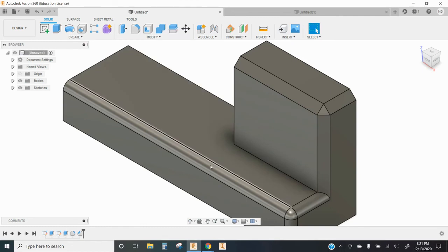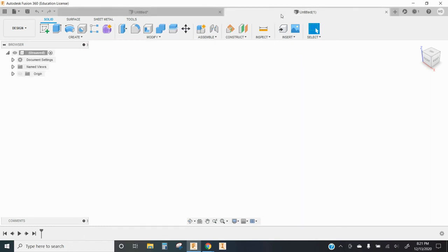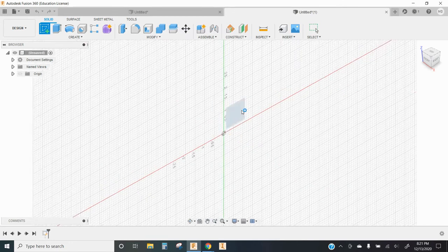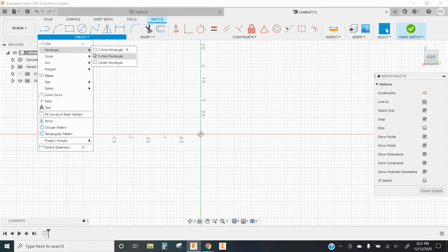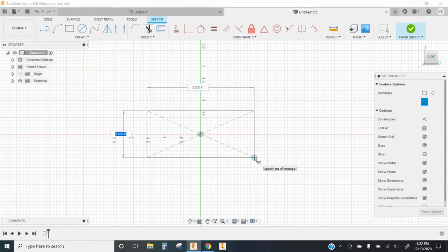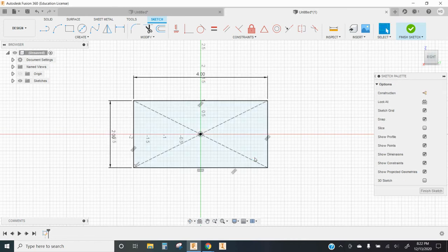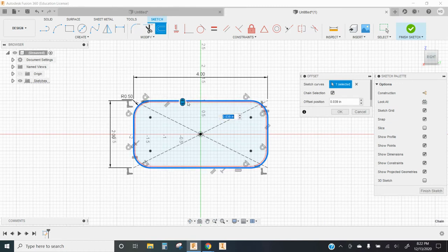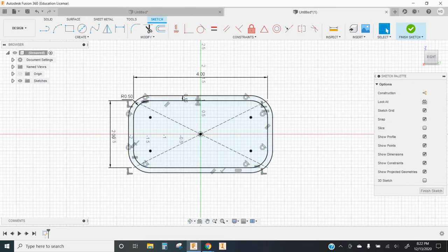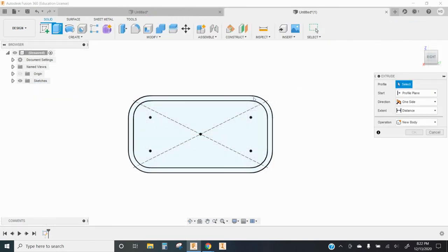Beyond these sort of obvious applications for fillets and chamfers, there are other ways to use these in designs. Like if, for instance, we wanted to model some rectangular metal stock, I could create the interior walls of that stock looking like this, and within the 2D sketch environment we have the fillet tool here, so I can apply a fillet to these four corners before even doing a 3D operation. I can offset that, and now I have a profile to extrude.